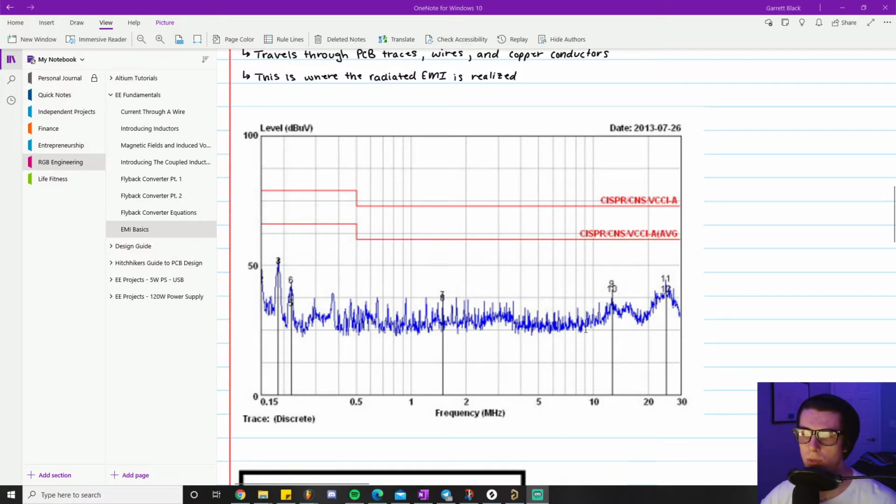You have some little squiggly lines going across, and you see across this frequency spectrum the levels of EMI that your device gives off. In this case, this one clearly passes because its levels are well below our threshold line. And like I said, you would have two separate tests per device, one for radiated, one for conducted, and you pass the same way in both cases, if it's below the required threshold.